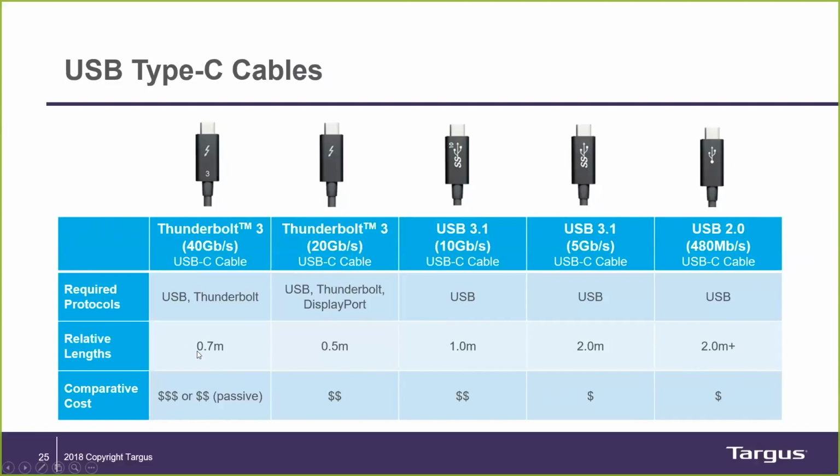The important thing to take away here is if you have a Thunderbolt connection, Thunderbolt to Thunderbolt, use a Thunderbolt cable. Look for this logo and be careful that it is just this logo, because I'm seeing knockoff cables that kind of look like this logo, but they're not. This is the logo you want, especially at 40 gig. Make sure you have it.